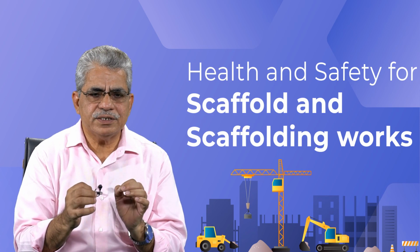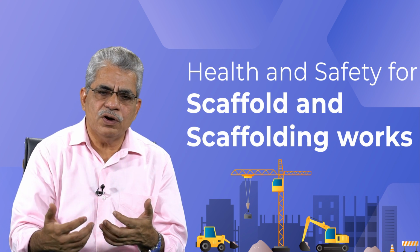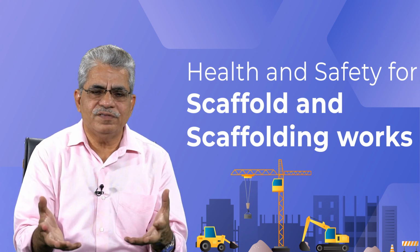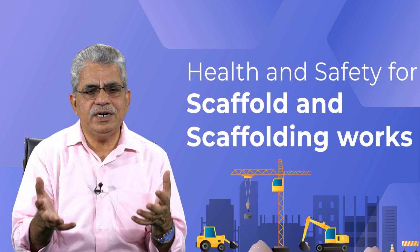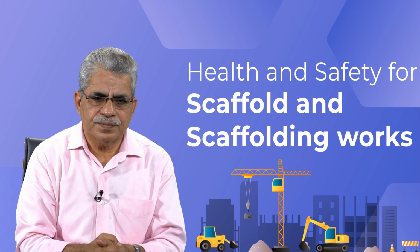Then next is overloading of platforms and scaffolds. As I told you, the scaffolds are designed keeping in view the load which is expected to come on the scaffold and its platforms. So if we are overloading these platforms and scaffold, then there may be a case of failure of the platform or the whole of the scaffold. So we should avoid the situations of overloading of platforms and scaffolds.